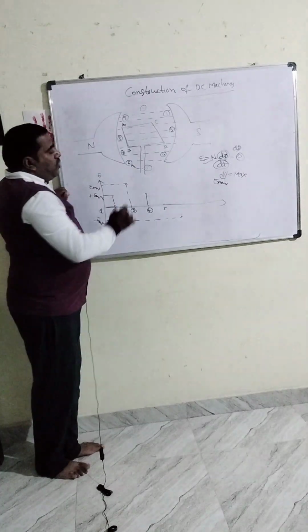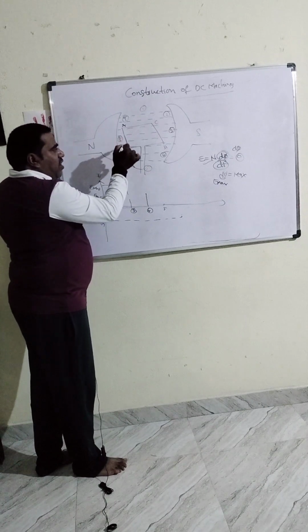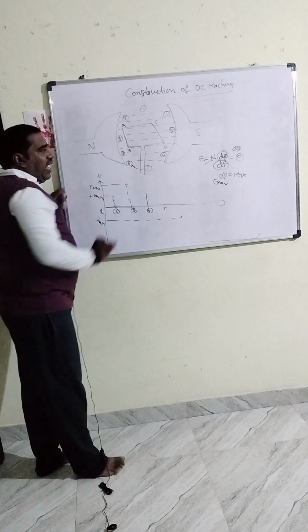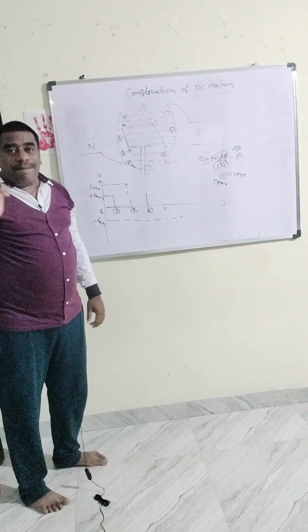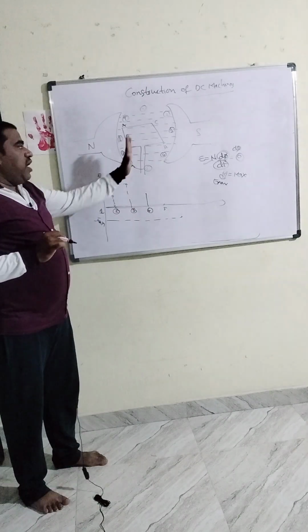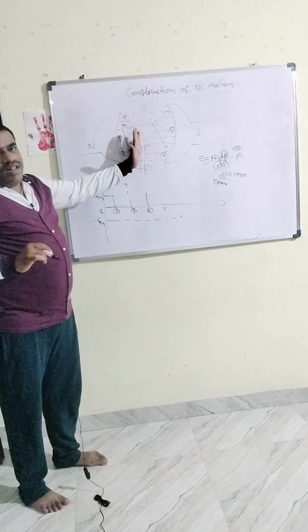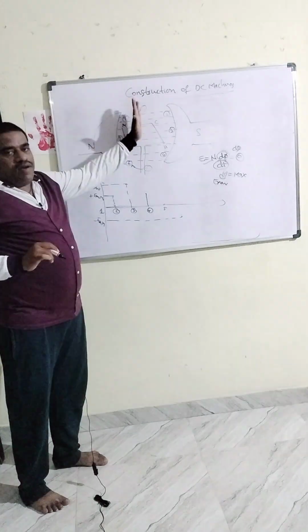When it is moving from 5 to 6, you may consider 7 here, or consider 8. If this small step is neglected, let's consider 8. When it is moving from 6 to 8, it should be perpendicular to the plane. Perpendicular to the plane means maximum flux lines are cut by the conductors, that is the CD coil side conductors, and this side will be the AB coil side.